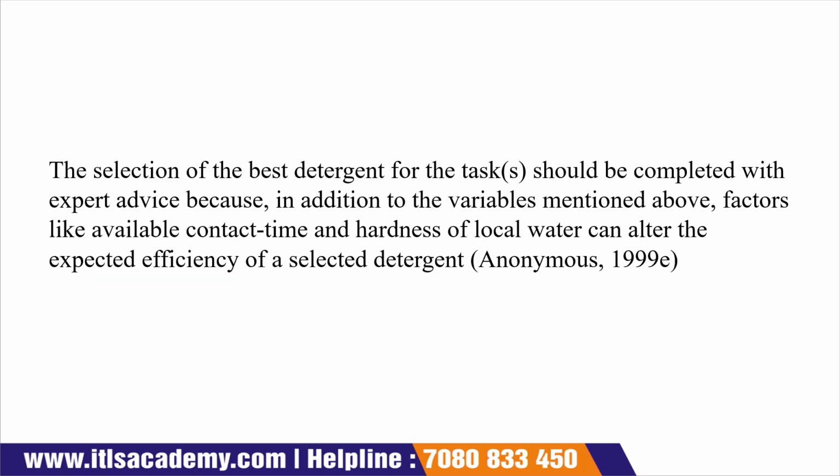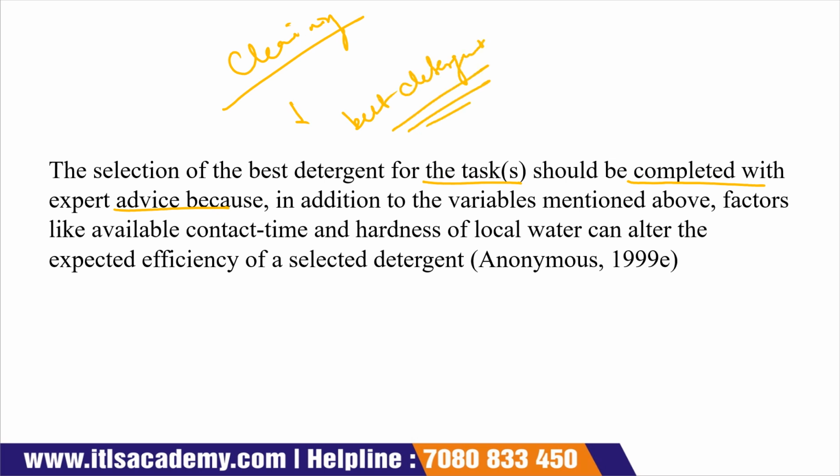Next, the selection of the best detergent for the task should be completed with expert advice. During cleaning we have to select the best detergent with expert advice, because in addition to the variables mentioned above, factors like available contact time and hardness of the local water can alter the expected efficiency of a selected detergent.